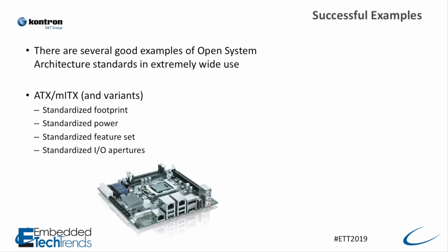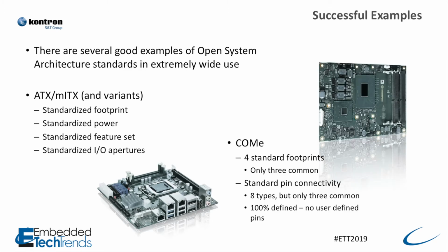One is the ATX, MITX family of standards. The community's pretty familiar with that. It evolved out of the desktop community. It follows standard footprints, standard power profiles, standard feature sets, standard apertures for I/O. But another example that's maybe a little closer to VPX, and to some of the problems this community tries to solve, is COM-E.